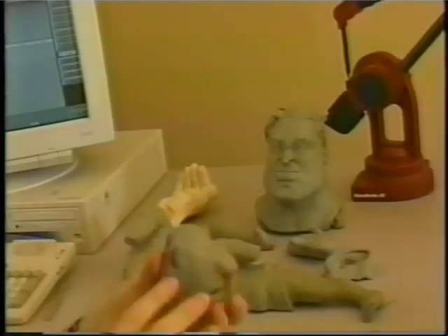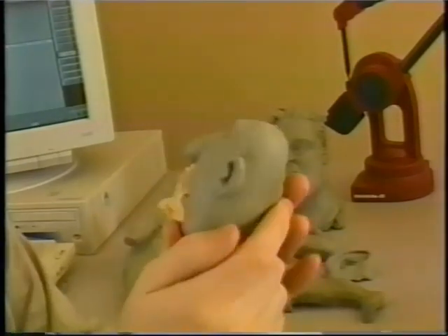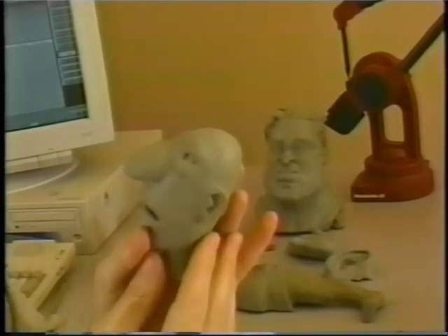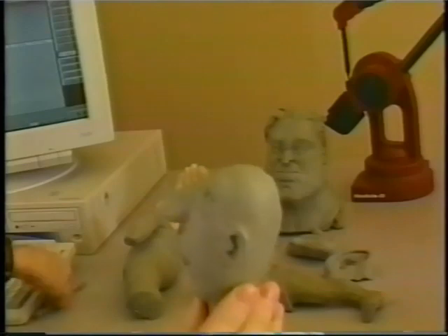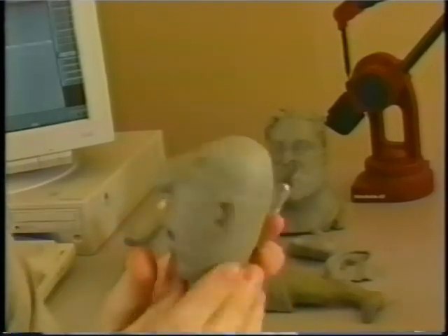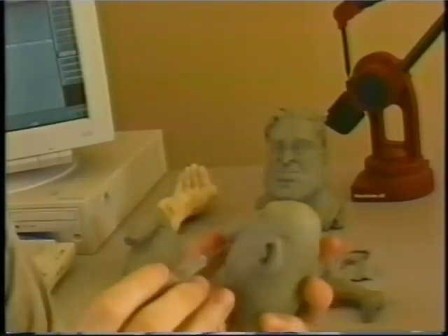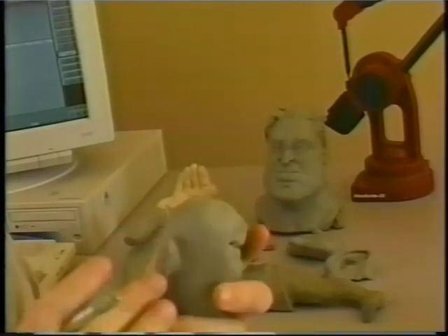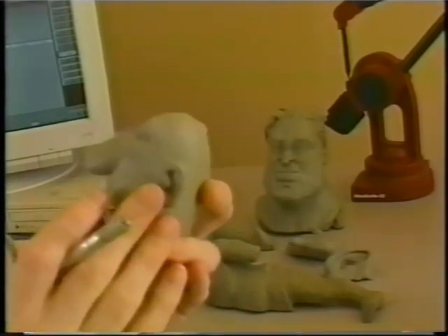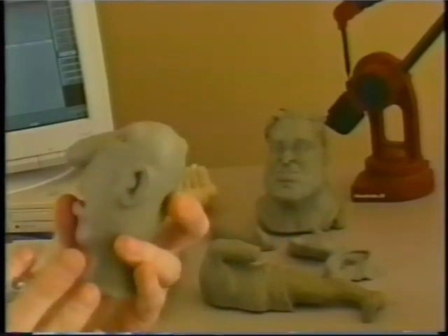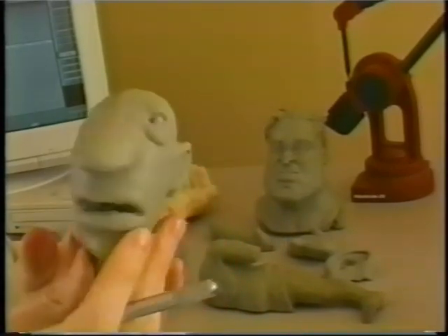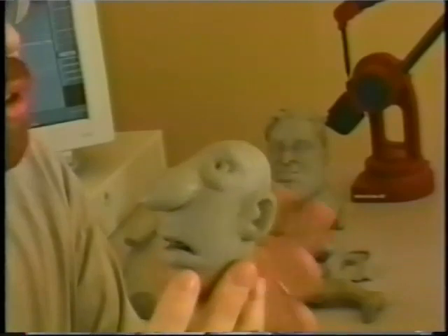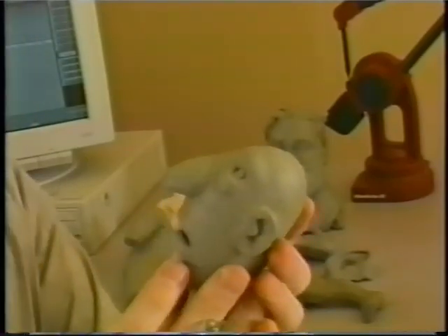Now going back to this character, we talked about ears a minute ago, but we could have included the ear into the geometry of the face. So if we had enough points, we could flow that in and out around the ear and catch all that and not have had to have a separate surface. But you need to weigh your options very carefully, because remember there are two opposing truths to NURBS.